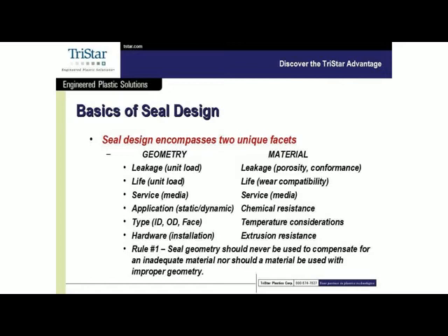So we look at the compatibility of the hardware, the media, the temperatures to be sure that we're getting the right fillers matched up with the PTFE. Again, looking at the service, what's the media: gas, oil, water, what is it? Temperature and chemical considerations. These are both critical, not so much in terms of the PTFE seal, but in terms of the expander material. If we have situations where we're introducing certain chemicals or certain high temperature or very low temperatures where elastomers are not going to work, that's where we're going to point you in the direction of a spring energized seal, which we'll talk about in a minute.